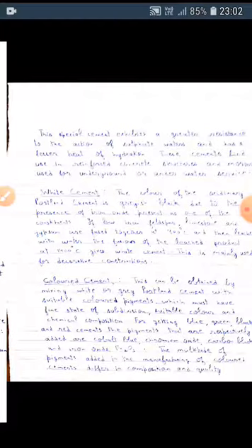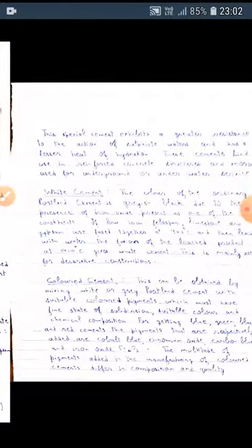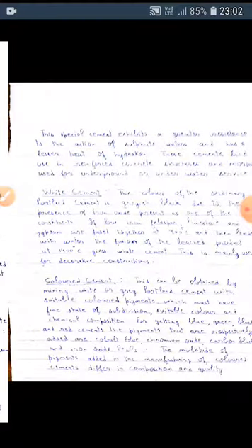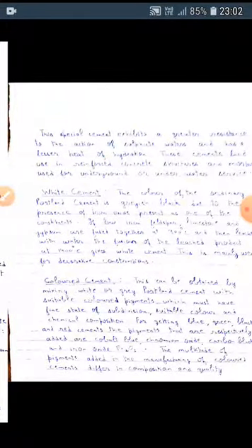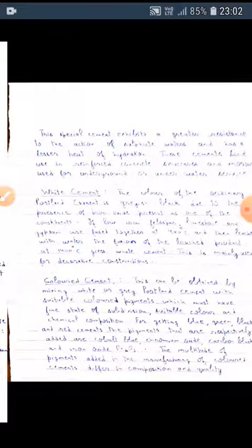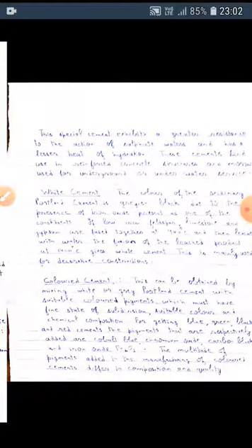The multitude of pigments added to Portland cement in the manufacturing of colored cements differ in composition and quality. Depending on the color design, the pigments are added to the cement: mummy, that is Prussian red, minium, chromium oxide, ultramarine blue, phthalocyanine, ultramarine green.